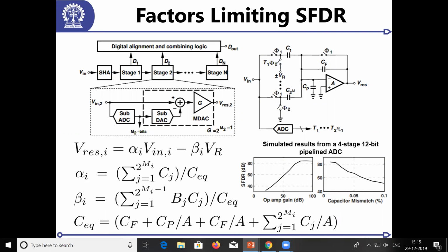No. You already have the 0.1 volt resolution voltage with you, right? Just giving you comparators. Right. No, actually, this is just an illustration. The way this voltage is added is not like this actually. You use capacitors and switch their capacitor to a certain voltage. This is just an example on the board to give you this. Right, but the capacitor also will be in the same resolution as what you need not be. That is the beauty of it.